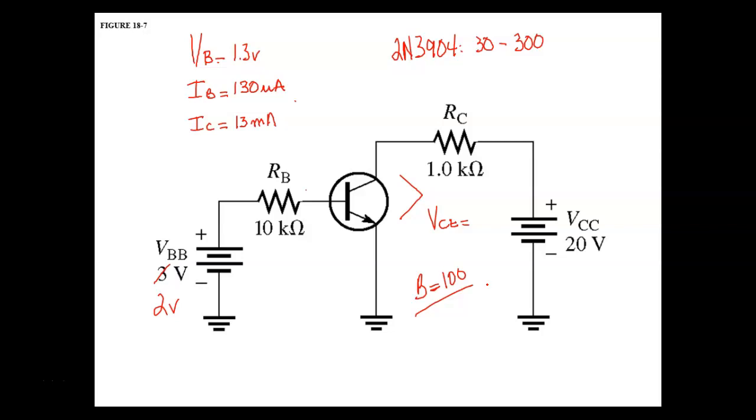You understand that? Now the emitter current is going to be a little higher, but what we're going to assume, guys, is they're so close to each other. Remember how close they were to each other? So for all practical purposes, we're going to assume, unless we give out a question, if I say IE is equal to IC, what are you going to say? Is that going to be true or false? That's going to be false. If I say it's approximately equal, then that would be true. So watch out for that on tests, because they are not equal. IE is slightly higher than what? Yeah.